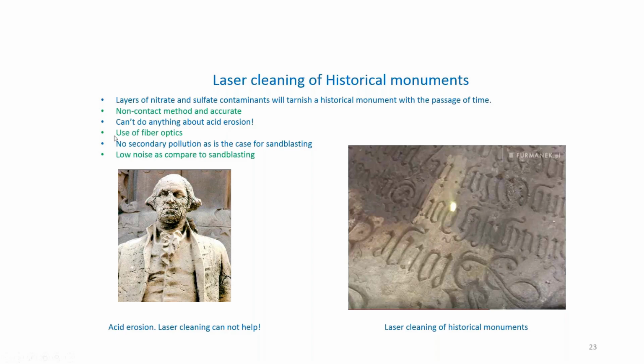So what are the other advantages of laser cleaning of historical monuments? It's a non-contact method and accurate. Use of fiber optics, no secondary pollution, as in the case of sandblasting, low noise, and basically it could remove the nitrate and sulfates, as we mentioned before.